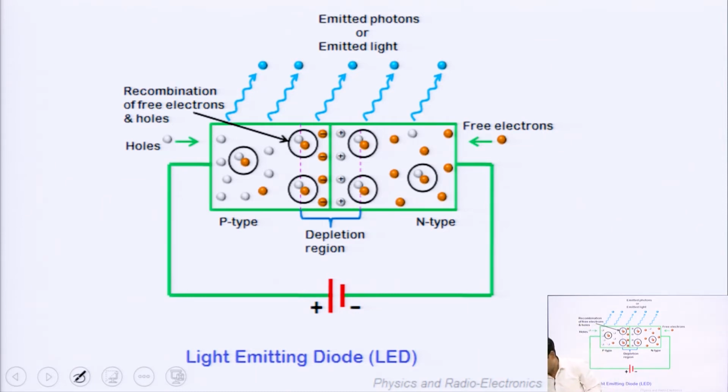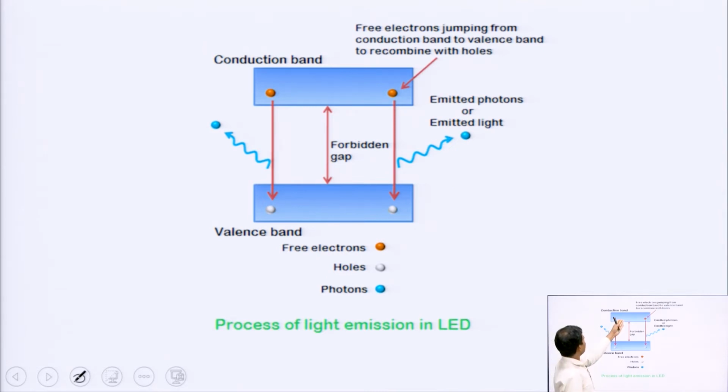And in the same figure, I am going to also discuss the phenomenon that radiates the color. Electrons fall to the valence band and it emits a photon. Okay guys, this phenomenon happens in a diode also, but there is no photon, there is heat, the other form of energy. In a normal diode, the energy radiated is not in the form of photons, but in the case of an LED, the energy radiated is in the form of photons.